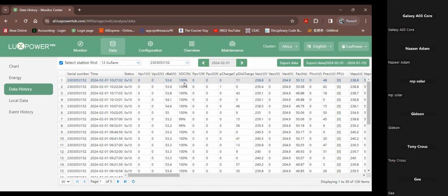Simply, and Volta as well, you need to contact your battery supplier and ask them if there's an update patch for the BMS, and they can come out and do it for you. They'll either send you the firmware and the BMS tool, or they will physically send a technician to come out and do it. And obviously, if you're using a Hino, there's no need for that because all of that can be done through the LuxpowerTek app. But that's an example of what happens with SOC drift.